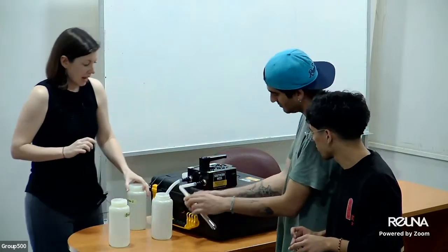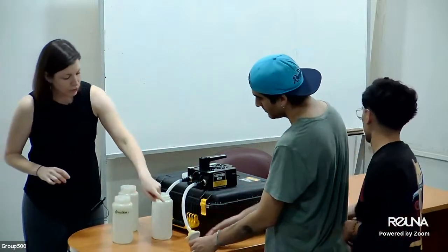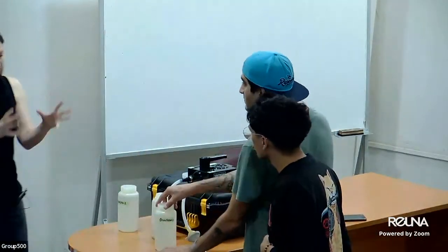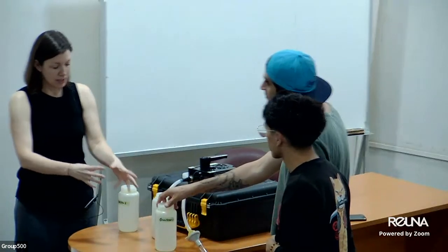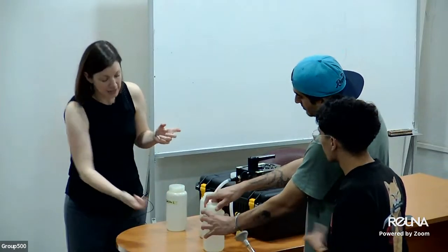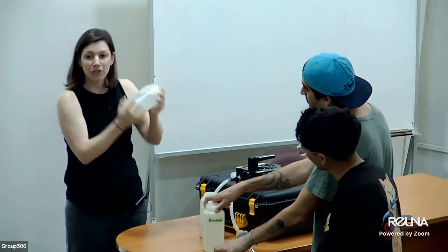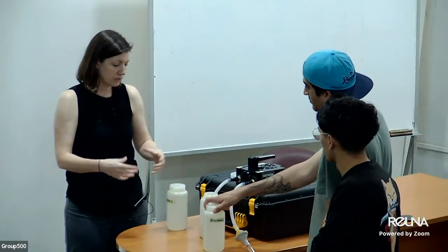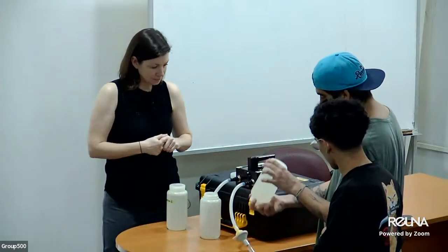Okay, and so what's going to happen is you're going to put the snorkel in the water sample, but before you do that, we're subsampling at each stage in the analysis, which you'll see. So we want to try and make that water sample as uniform as possible. So you're going to mix it. If any sediment has settled on the bottom, which it hasn't, you would resuspend it and try to keep it relatively even over the filter. So you can mix it, and then you can open it.